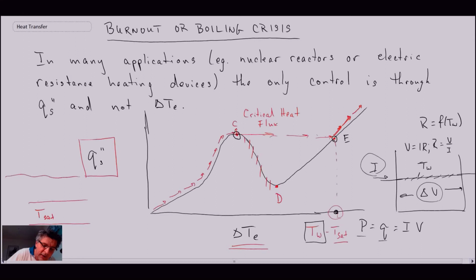And then you have your pool out here. So you're going to have two saturation temperatures, with two different fluids: one vapor going to liquid on the inside, and then your water out here. With that, you can control independently what the wall temperature would be based on the pressure. You'd vary the pressure inside, which would drive the saturation temperature wherever you wanted, and you could then control the wall temperature. And that is how the rest of the boiling curve data was eventually collected.